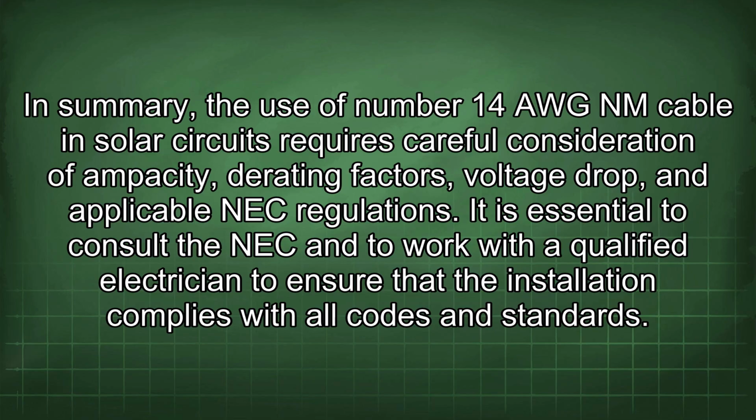In summary, the use of number 14 AWG-NM cable in solar circuits requires careful consideration of ampacity, derating factors, voltage drop, and applicable NEC regulations. It is essential to consult the NEC and to work with a qualified electrician to ensure that the installation complies with all codes and standards.